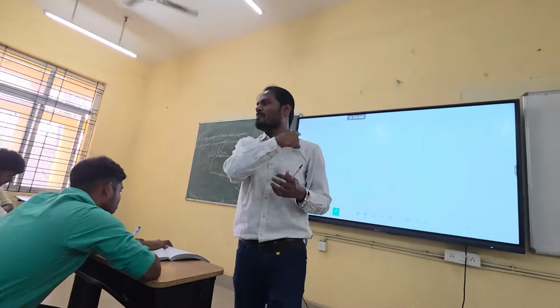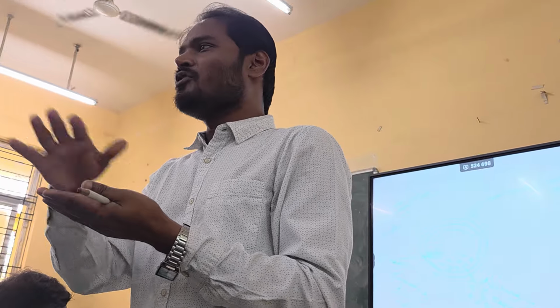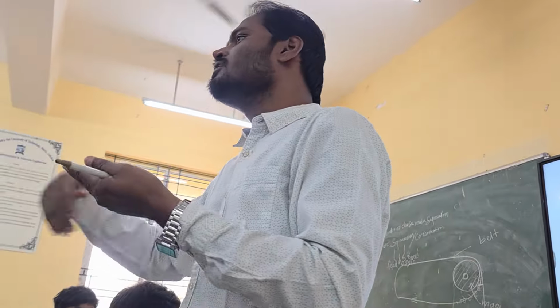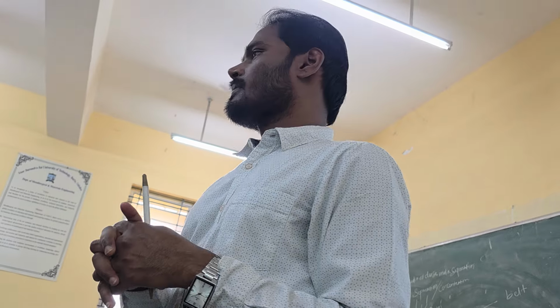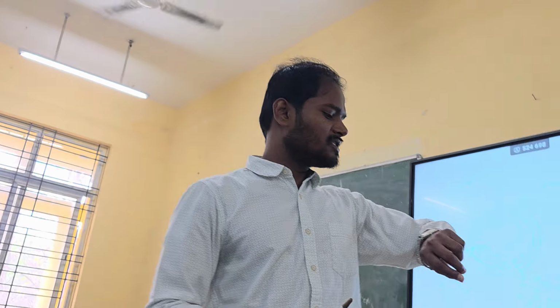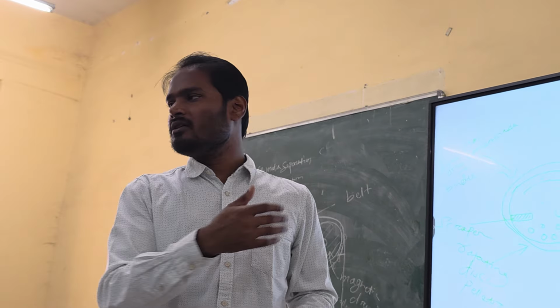And there is a scraper. Why is the scraper required? Otherwise it will stick. Because of moisture and binder, the fines will stick to the disc, so there is a scraper which will remove the sticky material. Okay, we'll discuss this in more detail in the coming lecture.